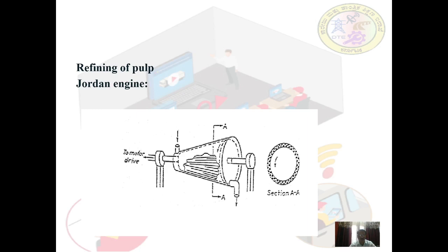All papers except absorbent papers like tissue paper, filter paper, blotting papers require fillers to give a smooth surface, a more brilliant whiteness, improved softness, printability, and improved opacity.